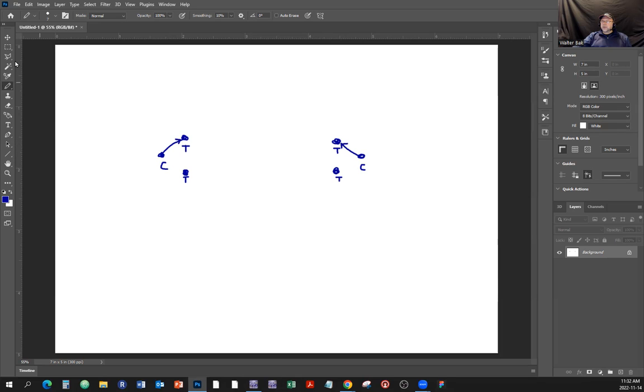All right, so the single pole can move between this and that, and this single pole can move between this and that traveler, independently. Now, in order for us to have a circuit, we're going to have some sort of a load. So let's say we're going to have a light bulb. Here is a symbol of a light bulb. Let's put everything in boxes. So I'm just going to draw a dotted line to indicate that these devices are in device boxes.